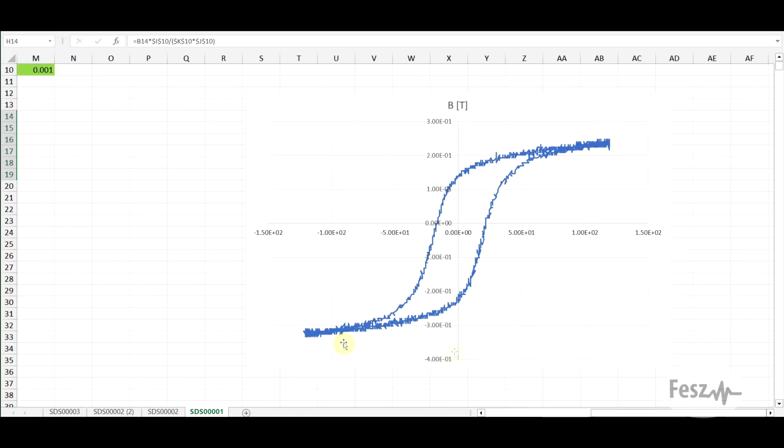So the graph does look as expected, we are getting the right shape. However, the thing that you might observe is that the graph is not really centered. The point of intersection on the top side is at around 0.15, whereas on the bottom it's at around minus 0.25. So there is an offset. And just like we saw in the simulations, this is happening because my probes are DC coupled.